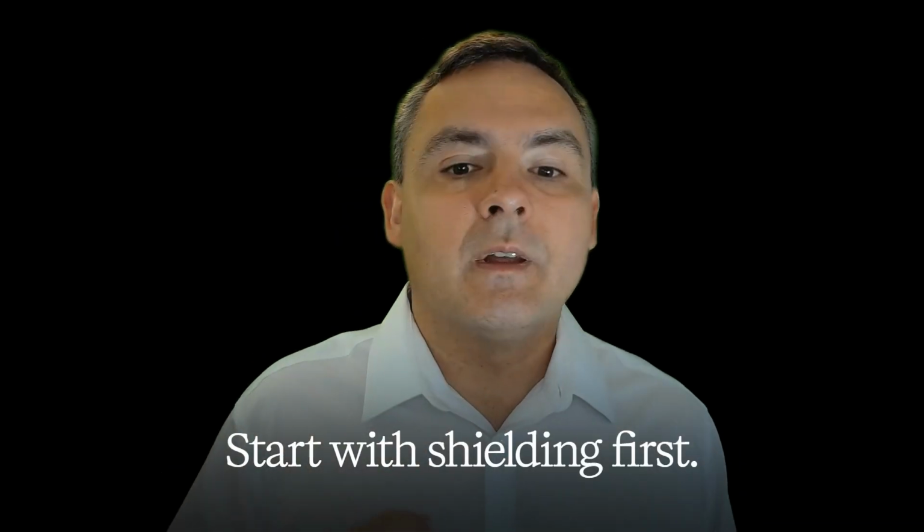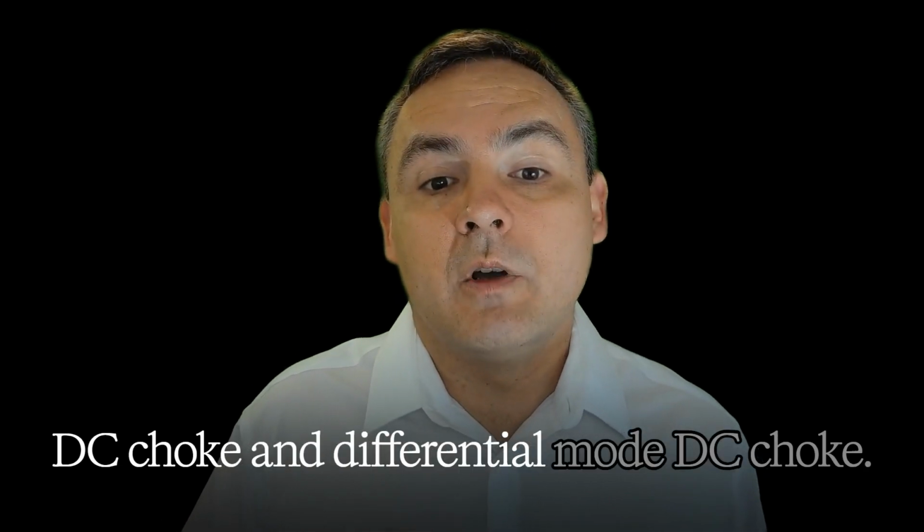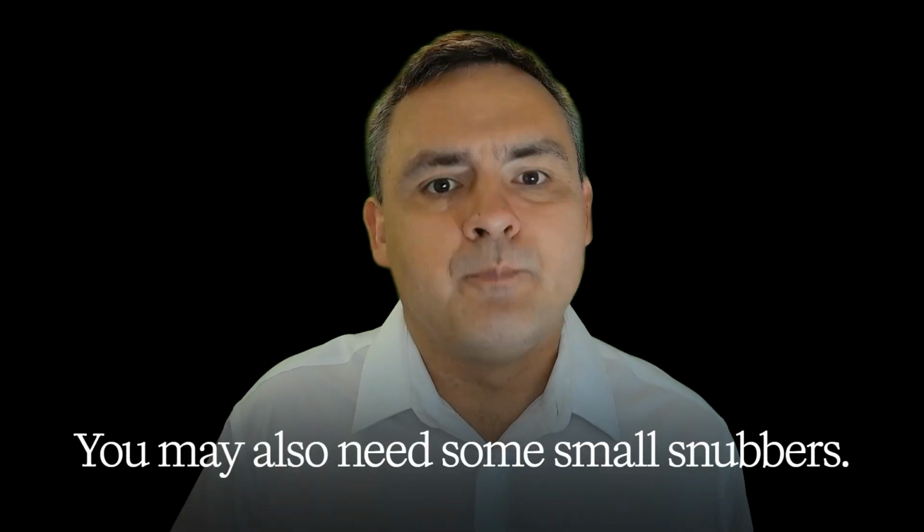I hope it is a bit clearer as to how simple it can be to mitigate noise in a high power DC system. Start with shielding first, then consider the use of a common mode DC choke and differential mode DC choke. You may also need some small snubbers. I hope this knowledge can help you become the DC power quality guru in your company.